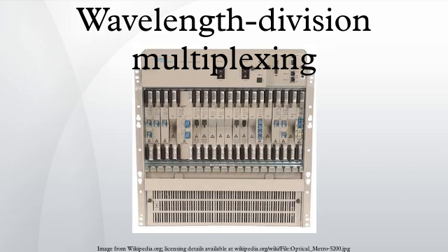This is often done by use of optical-to-optical translation at the very edge of the transport network, thus permitting interoperation with existing equipment with optical interfaces. Most WDM systems operate on single-mode fiber optical cables, which have a core diameter of 9 micrometers. Certain forms of WDM can also be used in multi-mode fiber cables, which have core diameters of 50 or 62.5 micrometers. Early WDM systems were expensive and complicated to run.